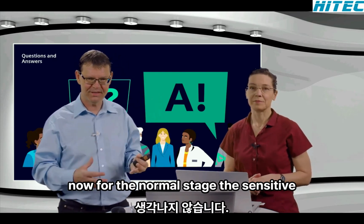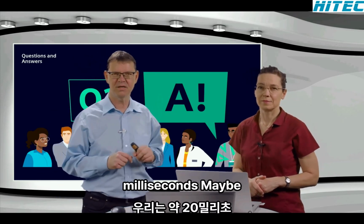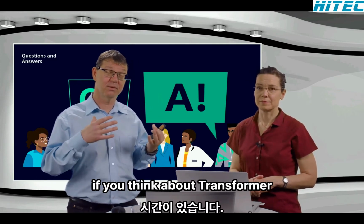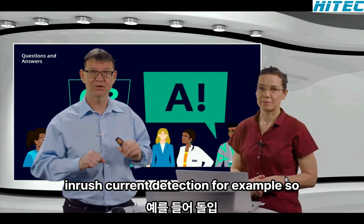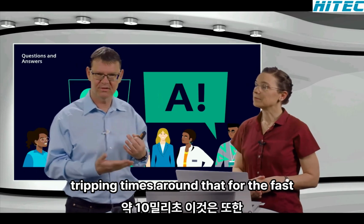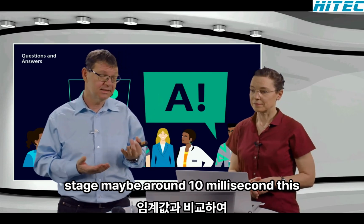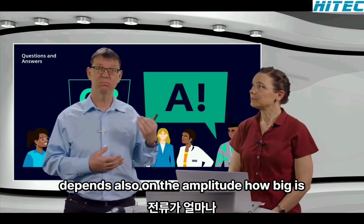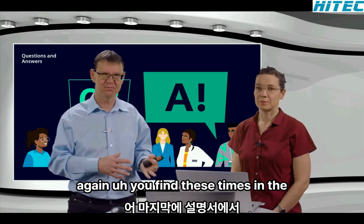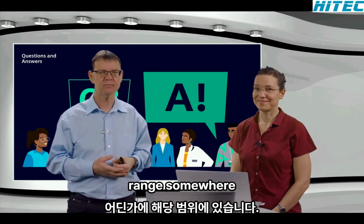For the normal stage, the sensitive stage, we have tripping times around 20 milliseconds maybe. Here you have to think about, if you think about transformer protection, we have to wait for the inrush current detection, for example. So we don't have this here, but we get tripping times around that. For the fast stage, maybe around 10 milliseconds. This depends also on the amplitude, how big is the current compared to the threshold again. You find these times in the manual at the end, but it's in that range somewhere.